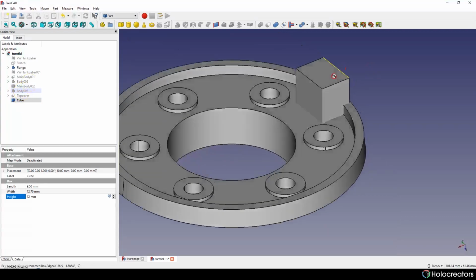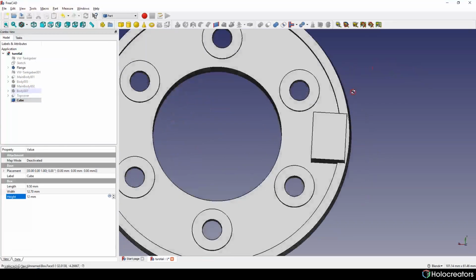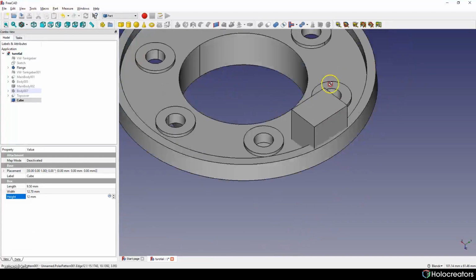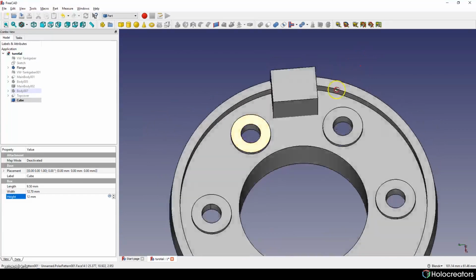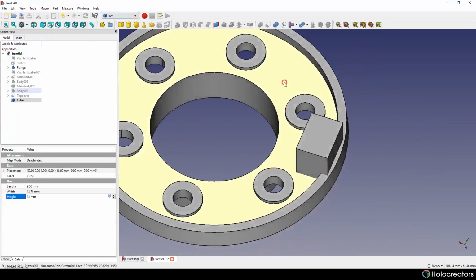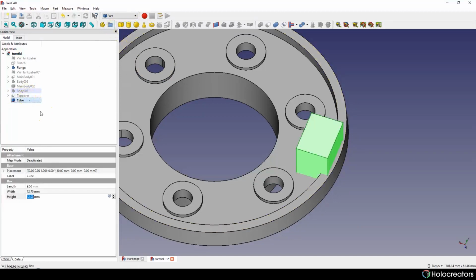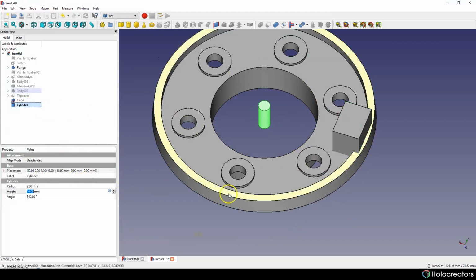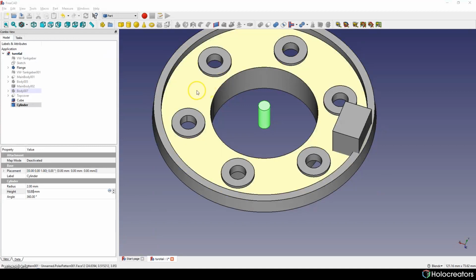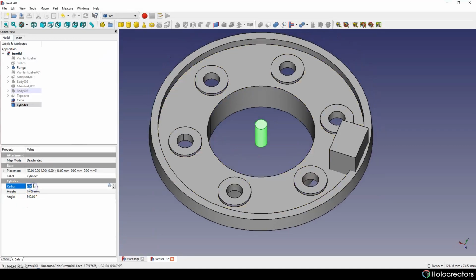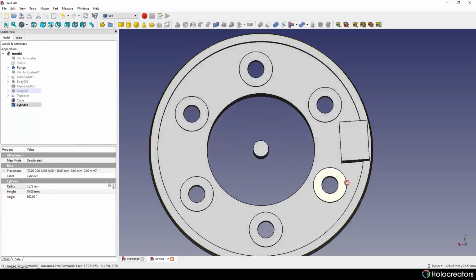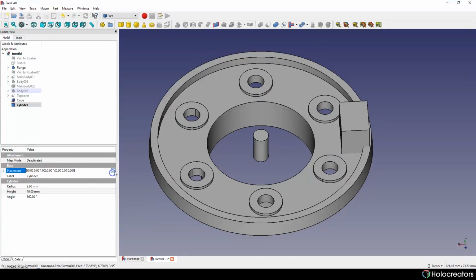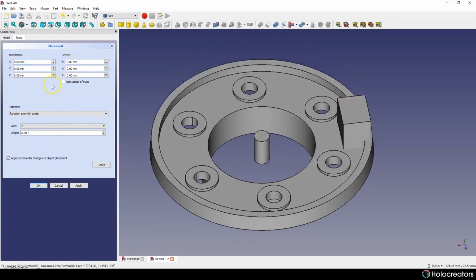Next thing, we have to create a simple cylinder here, and we're gonna do Boolean operation. Just need to make a cylinder, we need to make it 5.2 in diameter, so it's 5.2 divided by 2. And next we have to position it, so we're doing all the same things.